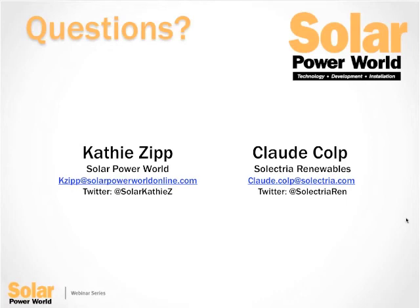That's actually a similar question to the previous one regarding TL inverters. So TL inverters are floating arrays because they don't have a ground reference. So currently the answer is no. The Arcom does not work on floating arrays. Okay.